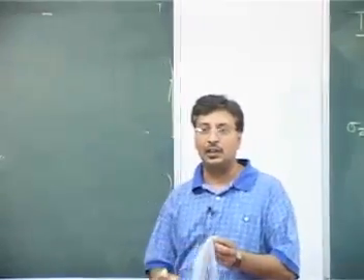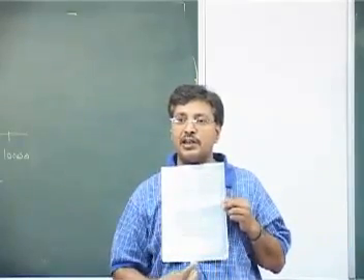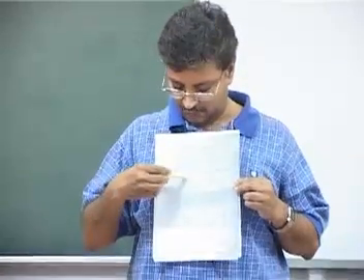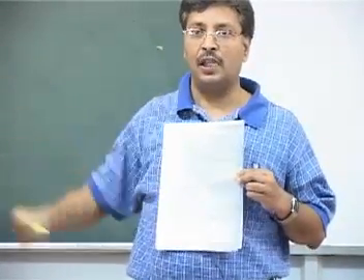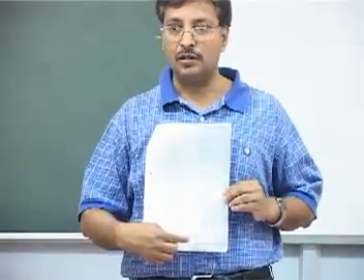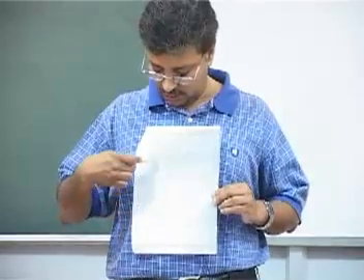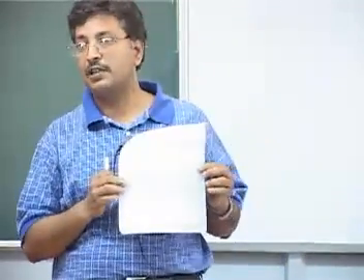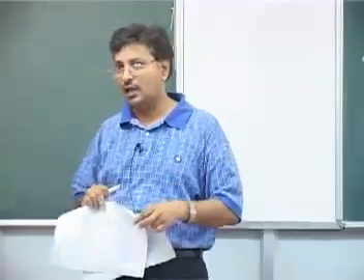I have the graphs, but I didn't bring the laptop. This particular graph, some of you in the front can see. This axis is downwind distance x, and this side is sigma y, and these are the values of sigma y for stability A, B, C, D, E and F. And then the same thing for sigma z, where you see more curved graphs, with the same downwind distance on a log scale, the value of sigma z on the y axis, again log scale, and A, B, C, D, E and F. You can find out the value of sigma y and sigma z depending on what x you are interested in and what the stability class is.